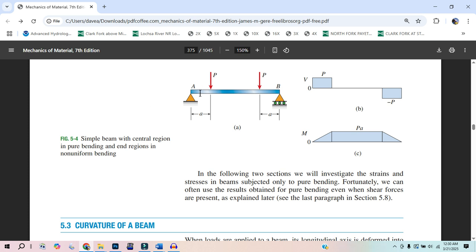But no, it's the fact that you can't have shear forces at the top and bottom, but we still have a number from an empirical standpoint that, if you have a force and an area of steel, let's say your average shear stress is 29,000 psi, and I have a surface area of an I-beam of, let's say, 10 square inches. It looks like I can apply a shear force of not only 29,000, but 10 times that. So 290,000 pounds. Now, do you think I'm going to drive something over a bridge that weighs 290,000 pounds? No, it's not the shuttle.